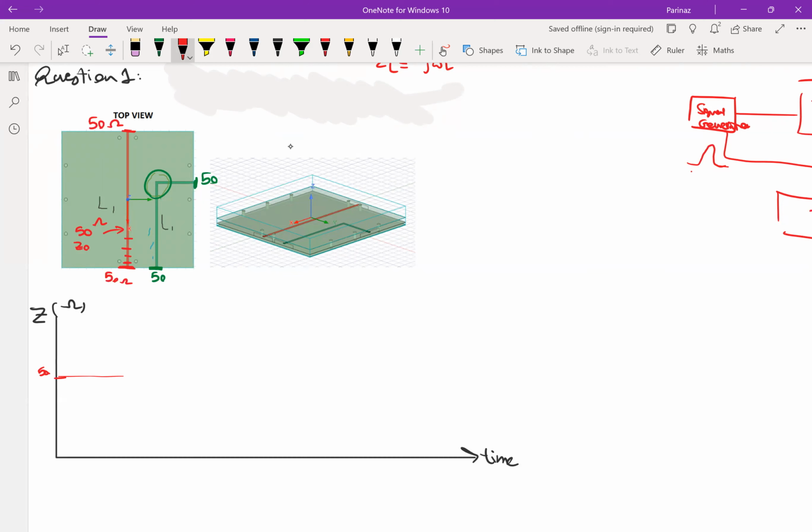So as it's traveling, I'm showing a length on the line, right? But it's indicative of the time as well. It's as if the signal is going forward, right? As it's traveling through different lengths of this line, the different time is passing too. So by the time it gets, let's say this is the end of the line for us, or Tmax, we always see 50 ohm, right?